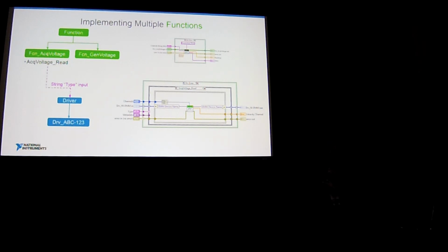it returns a voltage. And now I'm going to extend that same piece of hardware with one new function, and that new function is gen voltage measure. You can see at the top, gen voltage measure called read. It's actually trying to return, I guess, the output, or what it is outputting. So at the top, it calls driver read again, that top level function. It sends in the string gen voltage read, and now I have a new case structure. So to add one new function to this driver, I added one case structure. So this extends pretty well.